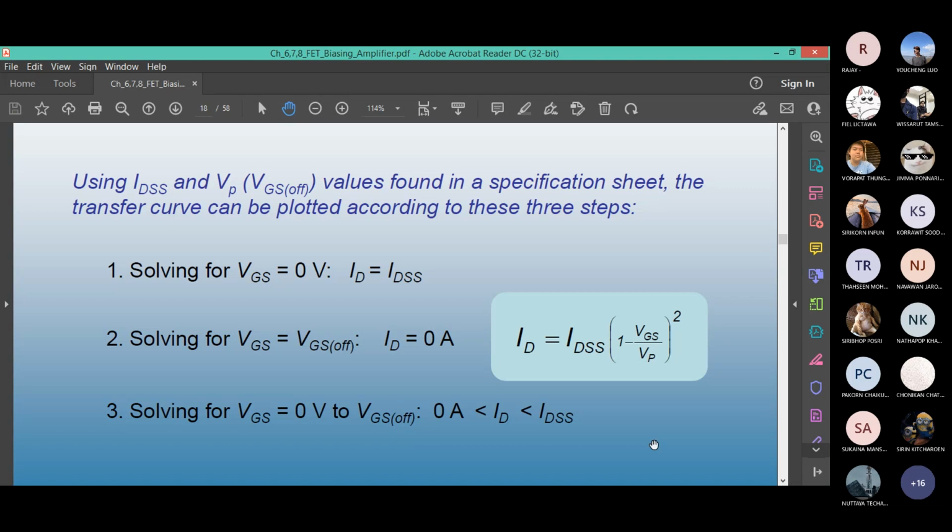Okay. So in this formula, if you put VGS equals VP, what happens? ID is 0, that is 1 point. And if you make VGS equals 0, what happens? ID becomes IDSS, you get the second point. And then I taught you two other shortcuts. What are the shortcuts? If ID equals 1/4 of IDSS, VGS equals what? Half of VP. You can plot that point. And then the fourth coordinate, when ID equals half of IDSS, VGS equals how much? Is it 0.3 times VP? I think it's 0.3 times. So you have 4 sets for quickly drawing the graph. Those are the 4 points you can find from this equation.